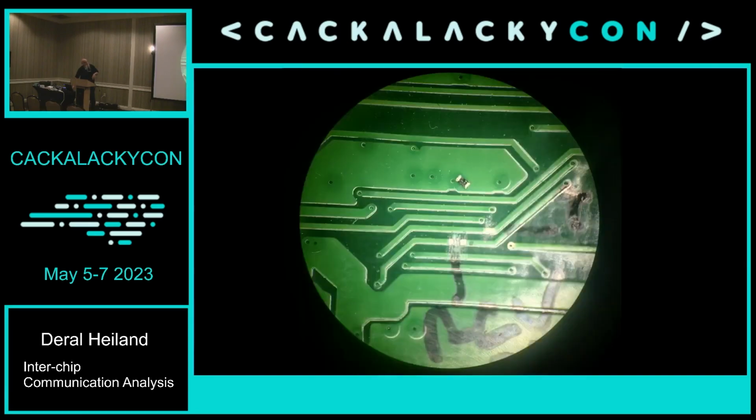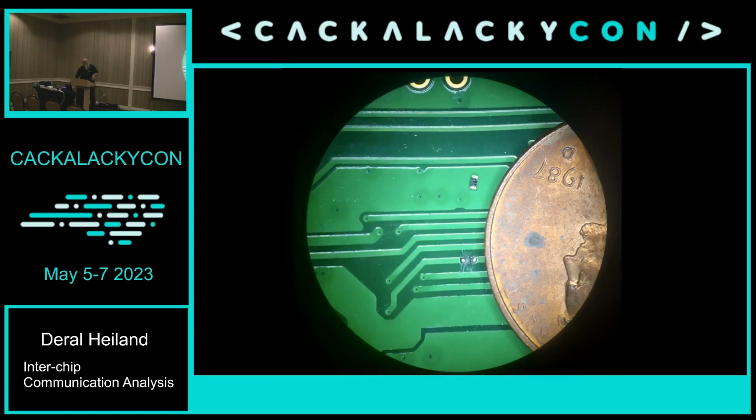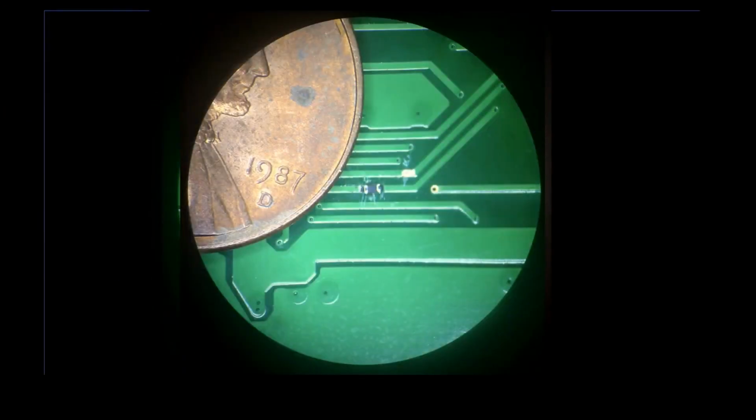So in this case, we actually cut the runs where we want to tap into it, and we put the resistor in circuit there. We add the resistor in there, and as you notice up here, I didn't cut the run yet. We are going to cut the run and tap into it. But the reason I didn't was I knew for sure if I cut both those lines, I'd end up soldering the resistor in the wrong spot. So I made sure I didn't cut both of them at the same time.